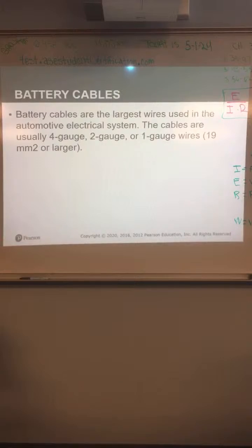If you disconnect the negative battery cable, the whole electrical system's dead. So then you can move the ground. You should remove the negative battery cable, not the positive. That way you can't short out on something, and also the negative is typically easier to remove. Sometimes positive battery cables have fuse panels attached to them. So the negative battery cable is always the one you're going to disconnect, okay? You may have to disconnect both of them depending on what you're doing, but for the most part, disconnecting the negative battery cable is all it takes.